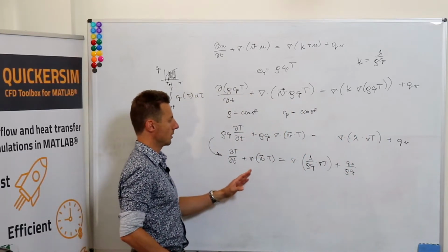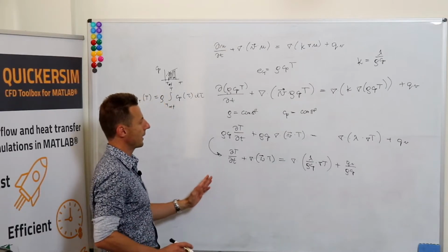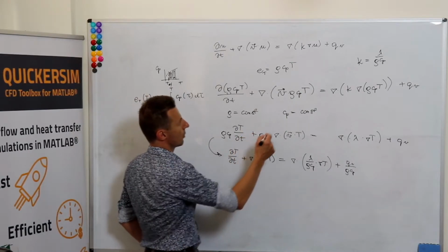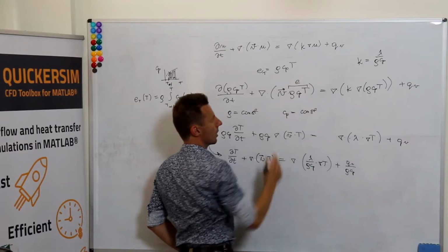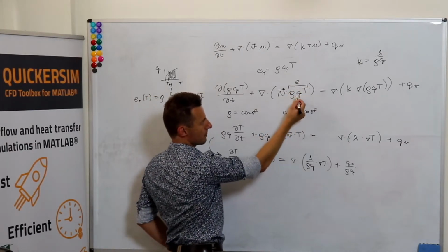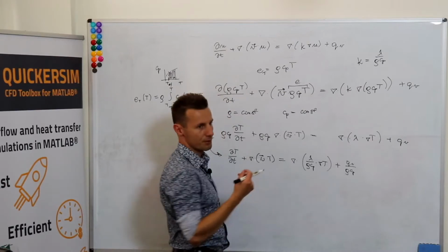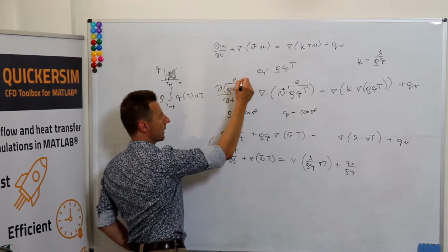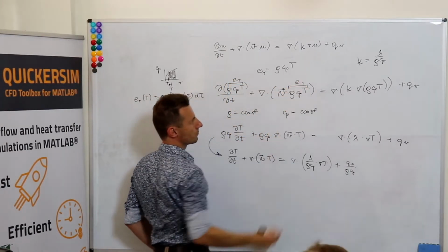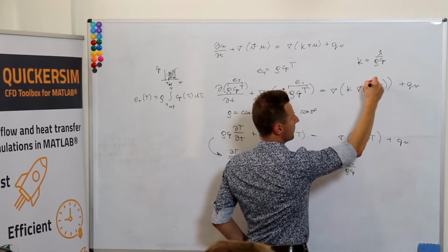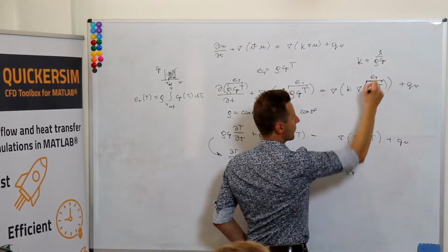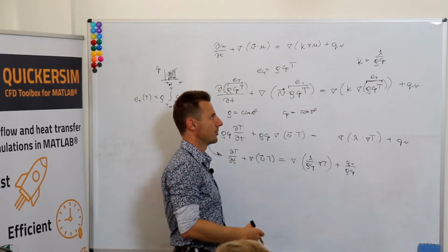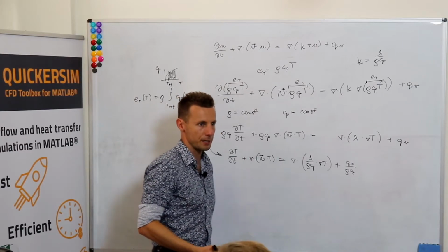So it's better to focus on energy conservation, and then what you need to do is you're basically writing the equation for convection of E. Here it's also a linear case because we simply multiply it by Cp. The most general form is simply saying, let's write the equation for thermal energy. We will be diffusing thermal energy.